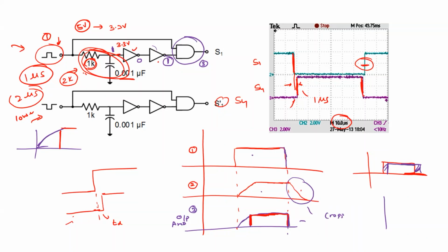Okay? So this is how we provide the time delays using hardware circuits, or analog circuits. The thing we need to remember is that the time constant of this RC will dictate the delay time. Another thing is connecting these two NOT gates back to back, which gives you sharp rising edge pulses.